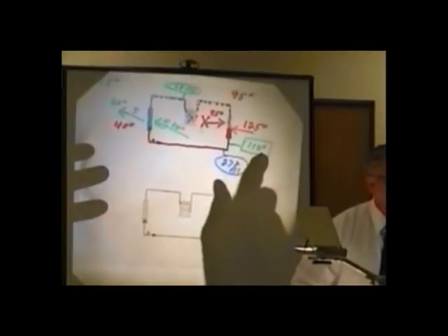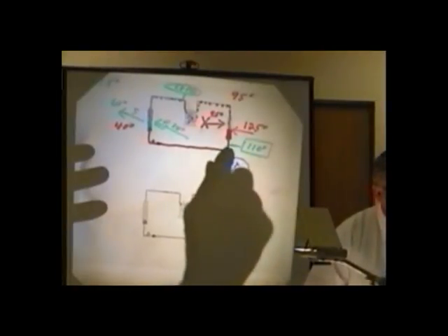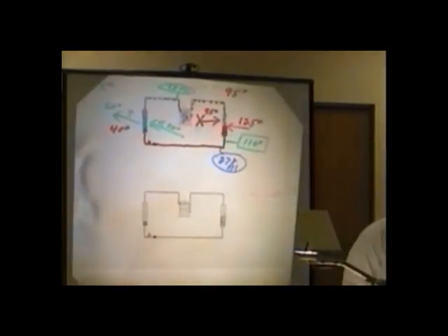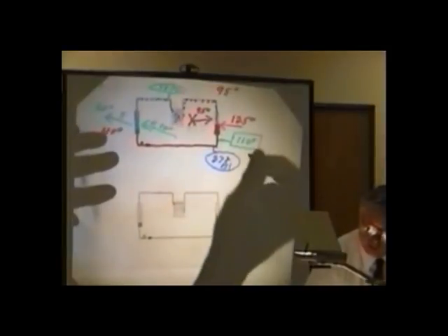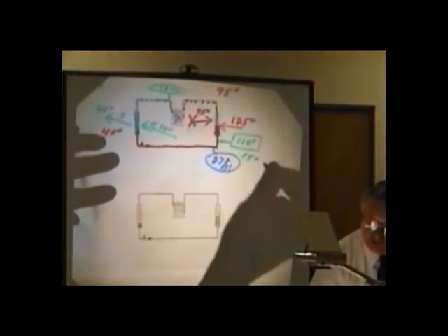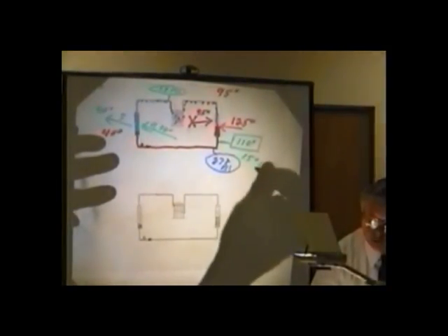Well, how many degrees difference is the bottom of the condenser as compared to the saturation temperature of the condenser? How many degrees cooler is it? 15. Gentlemen, that means we have 15 degrees of subcooling.